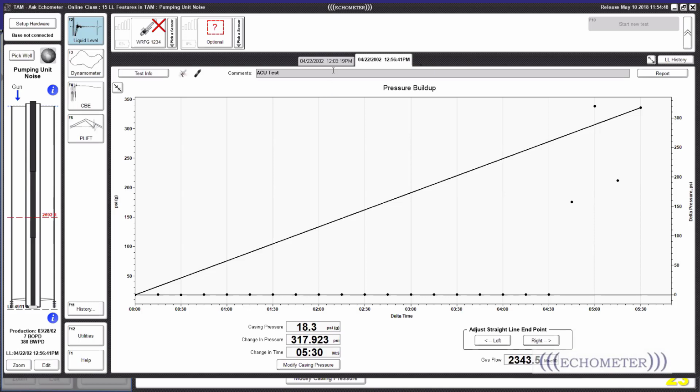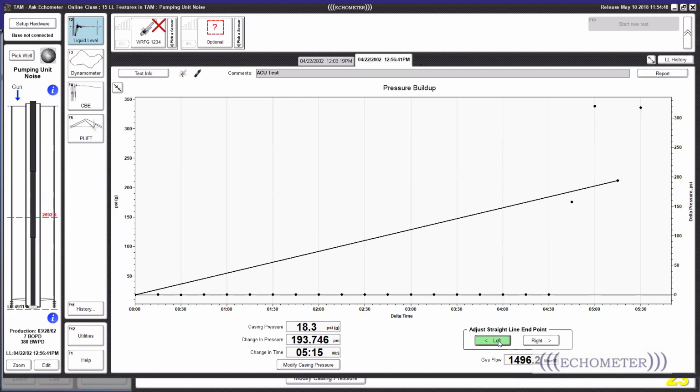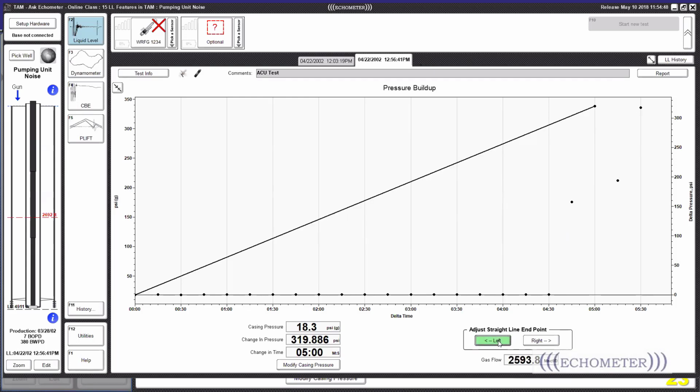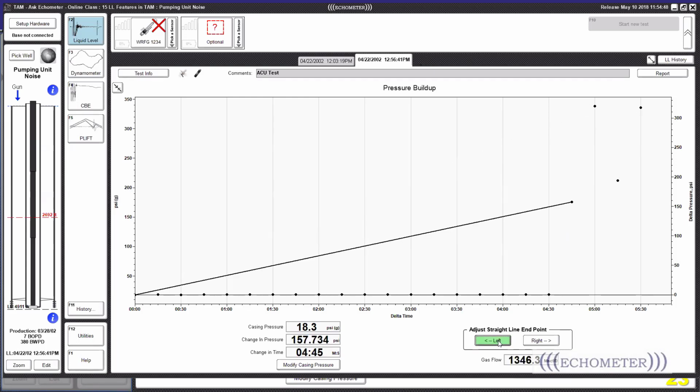That was a second shot, and they are ready to go to the next well. When they do that, the software or the pressure transducer will read any crazy value, and then we'll have pressure points all over the place. And this is going to over 2,000, or well, that would be 2 million MCF, and that's of course not real. That's just because they disconnected the cable.